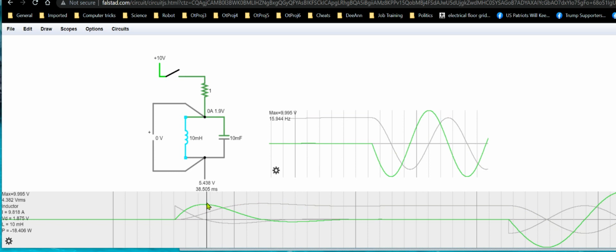So basically the capacitor's current starts going negative after a while, because it's actually starting to dump its energy into the inductor as the inductor is still continuing to charge. So once we get up to about here, the inductor is at 11.4 amps. Okay, whereas it should just be about 10 amps going through it, which is what it will have continuously. But right now it's at 11.5 amps, and that's because of that extra energy from the capacitor, which is still in the process of discharging.